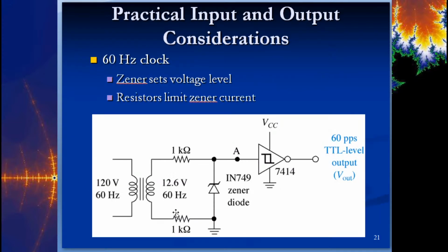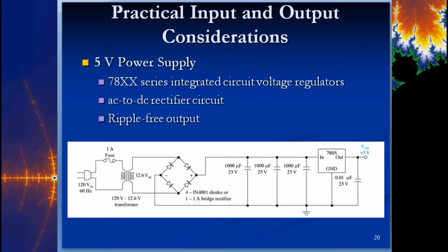And then the next part of it is maybe connecting up just a Schmitt trigger right out of the secondary of a transformer. Couple of 1K ohm resistors in series with the 2 leads, put a Zener diode in to get the 5 volts out, and then this will give you nice crisp lines. It'll take the sine wave and actually make it a square wave, okay? And this is actually TTL level if you use the same transformer. So these are the kind of little projects and little examples that Kleitz uses in Chapter 11, last part of Chapter 11, okay?